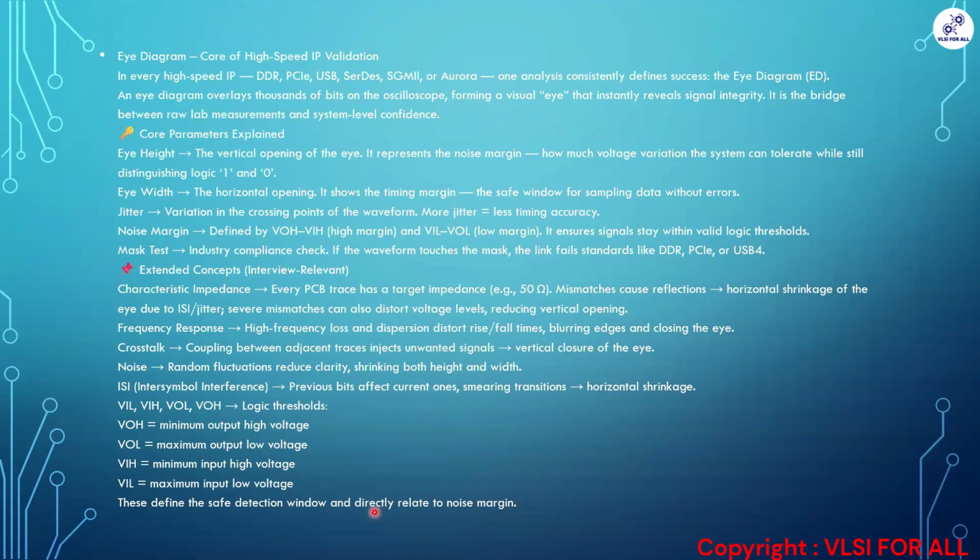When we open an eye diagram, we get two custom measurements. We can set the amplitude, and we get some histogram readings. So we can set it using the oscilloscope options of bit rate measurement and clock recovery. If you have the oscilloscope, it will be easy to explain, because the options are present in the oscilloscope.